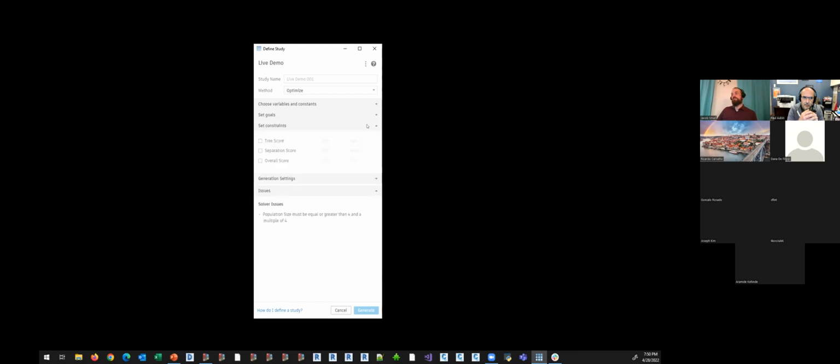Then from there, we set our constraints. I do not recommend playing with constraints until you get much, much further along in your studies within generative design, because effectively what this is going to do is if a result comes back which is outside the range that you specify, it doesn't count and it tries again. So you can imagine within that large number, 65,000 possibilities for just the inputs on this study, what number of those are going to have values in between whatever you think might be ideal? It's a small number, right?